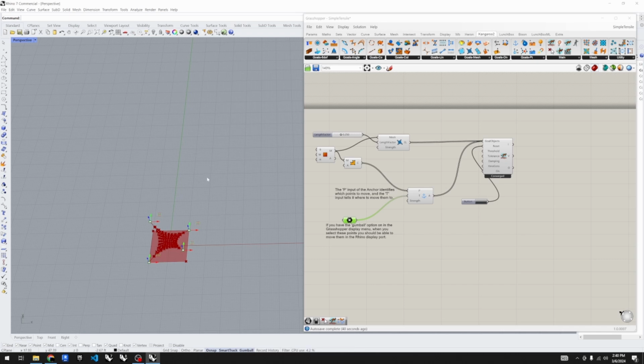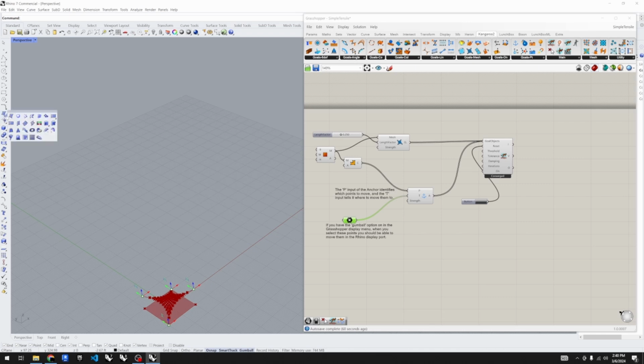My thought was, let's make something a little bit more like Frei Otto's kind of pavilion, where we have a radial form with some verticals. It looks a little bit more like a tent structure. In order to do that, I'm going to make some Rhino geometry. So I'm going to come into my surface, click on the little sneaky button here, and make a rectangular 2-point surface.